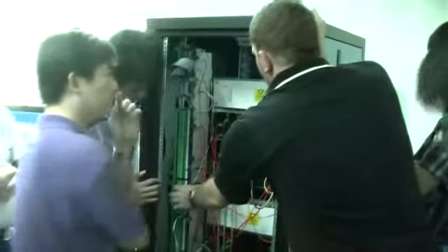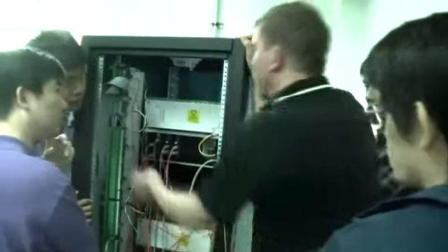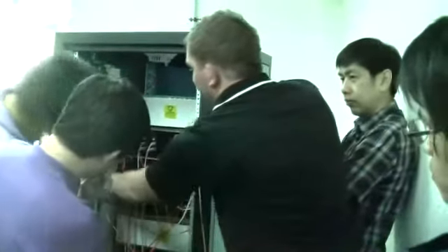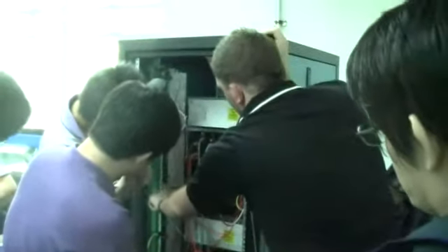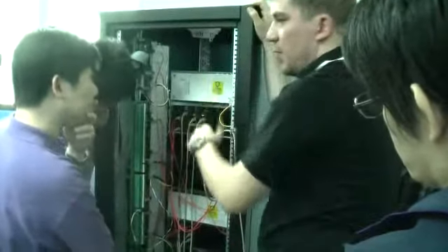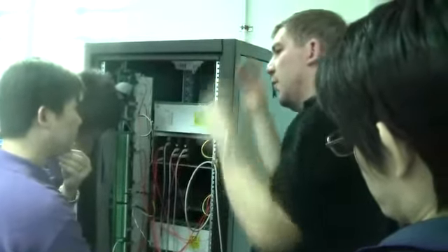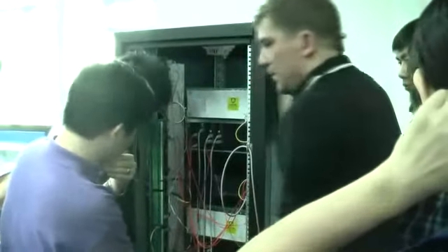Yeah. This, we don't use this card. That's output, right? Yeah. If we used it from the relay trip signal, we bring it to this one, input. Oh. Yeah, sorry. But then this isn't dry contact, so we still have to supply a voltage. We would have to supply maybe 5 volts to each terminal, right? So it sits high, and when the relay closes, then it shorts. So you can use it, but typically we use the front panel.